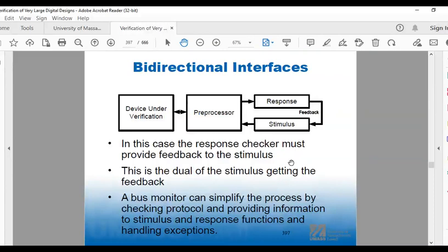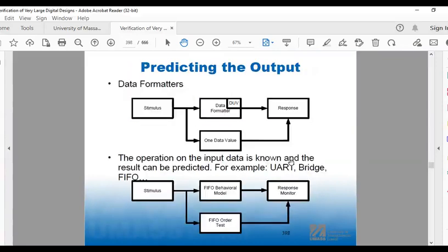I can't generalize this because it's going to be different for however you set up your tri-state drivers. So just know that that's harder, right? That bidirectional buses are harder. And it's harder because you don't know what direction they're in just by looking at it.